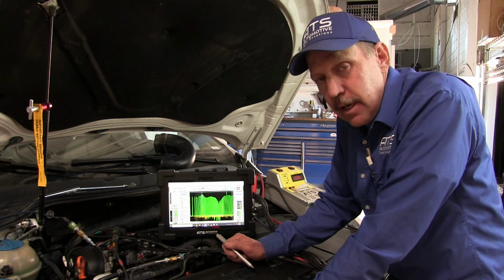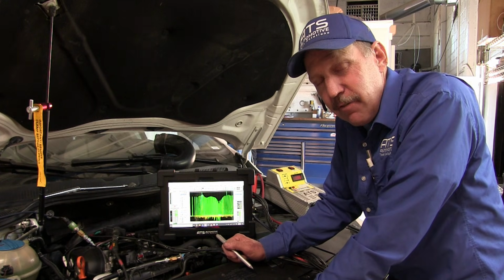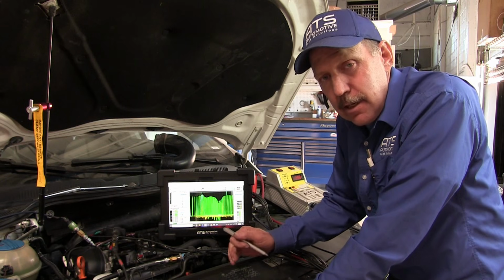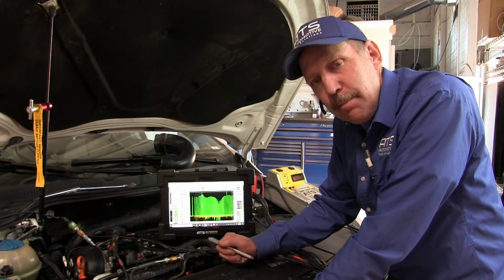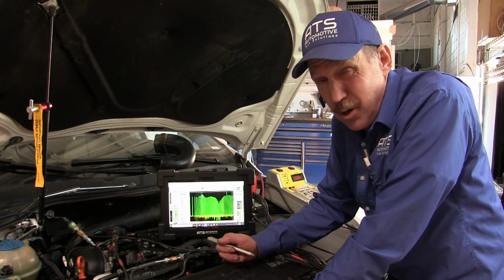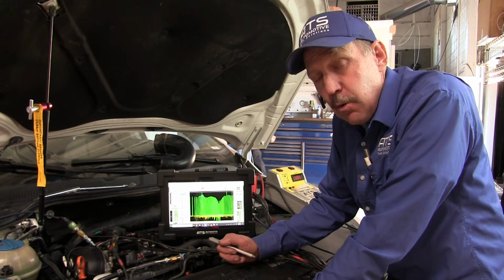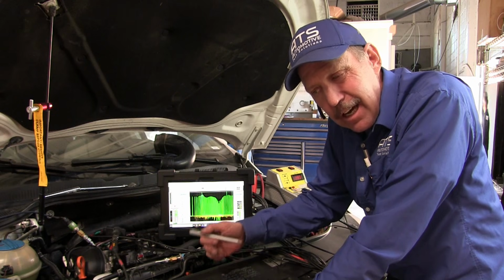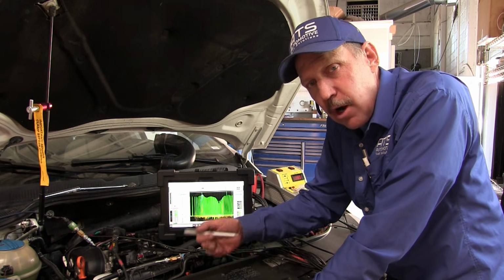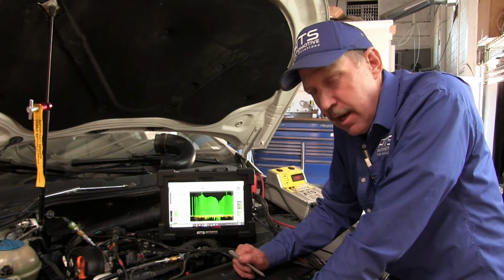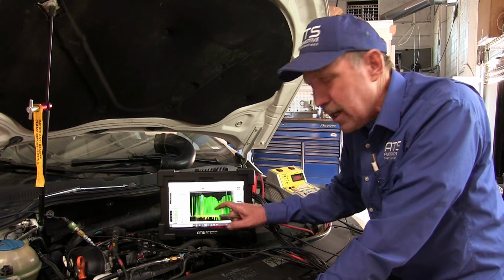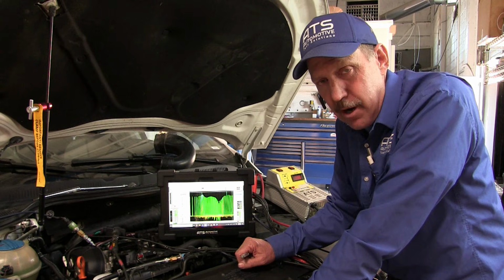In this case, I have a problem. It's indicative of a problem. I normally need to have 40 to 70 pounds at idle. I can go up to 100 pounds and that's okay, but when I start getting over 100 pounds, I've got to start asking myself, where did all the additional air come from? 180 pounds is way too much air. It's showing me I have a problem.